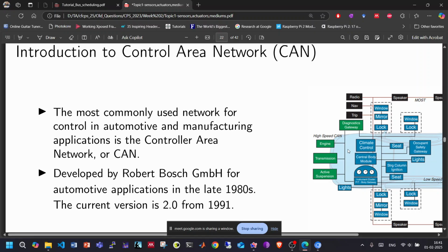Yes. Maybe at the same time, since it's a bus architecture, transmission is trying to send a 0 bit. What will happen? What will go through the bus? Transmission only. So you see, this is an AND phenomenon. Two signals are ANDed.